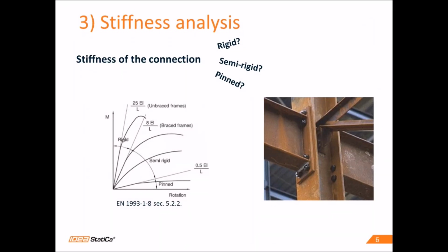It's about stiffness analysis. According to the code EN 1993 clause 5.2.2, we can classify the behavior of the connection into three classes: rigid, pinned, and something between. It's called semi-rigid.